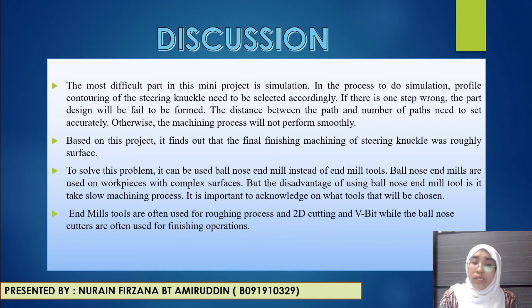It is important to acknowledge which tools will be chosen. End mill tools are often used for roughing processes and 2D cutting, while ball nose cutters are often used for finishing operations.